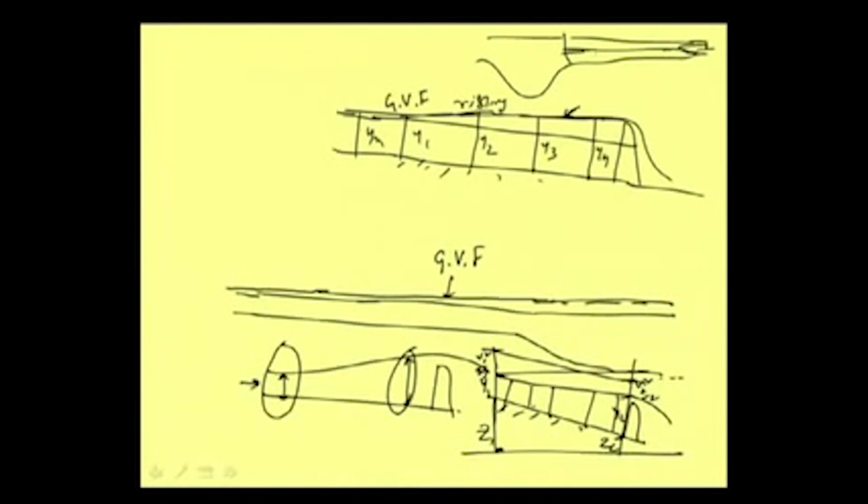So, there will always have to be more energy here than energy here, and then only this flow is occurring, and in reality it is like that. And this change in depth is so gradual that when we go to a field, it is not that visible. That means, on the upstream of a barrage or upstream of a weir, if we just observe the flow, we will never feel that the water depth is rising.